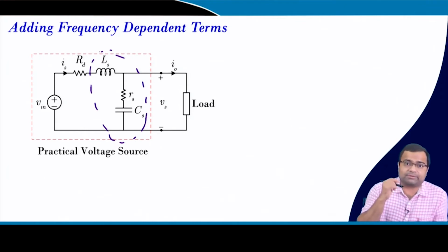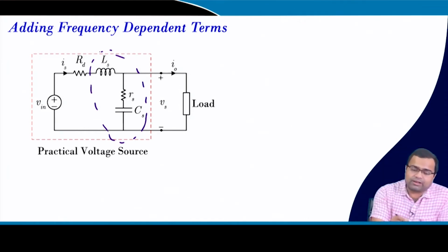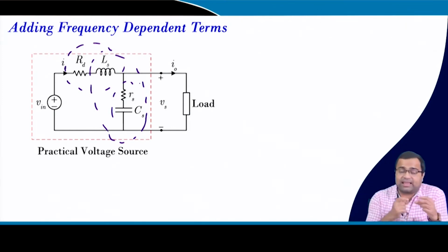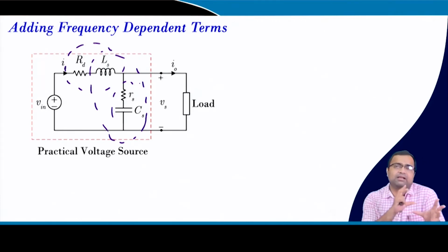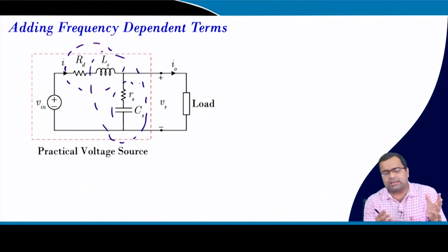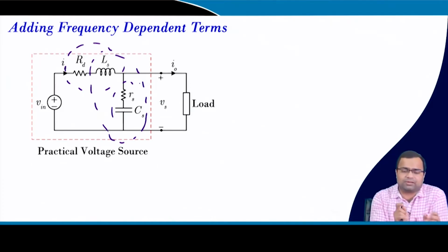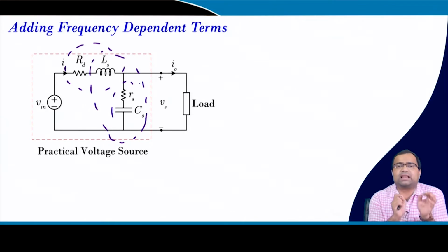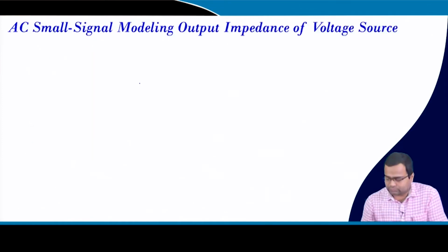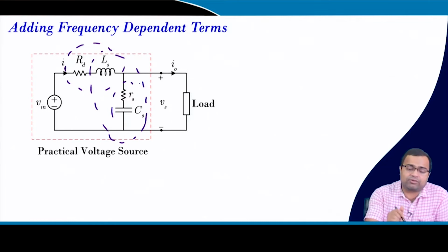If you take a step-down DC-DC converter, a buck converter, we know that the inductor L is there on the output side, and the capacitor is also there on the output side. From applying that common sense, we can think of an ideal voltage source as having some amount of finite inductive and capacitive effect. You may model it in a more accurate way, but this is one of the simplest ways to model it, which can capture the transient behavior, or the finite bandwidth aspect, of a voltage source. That means this is what we are going to use.